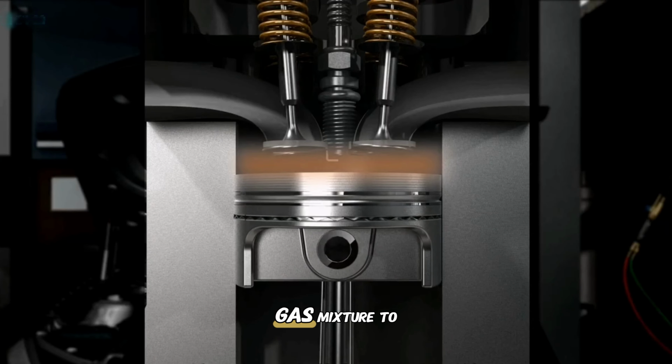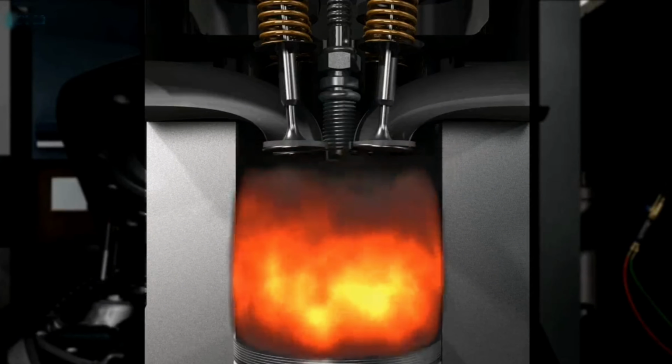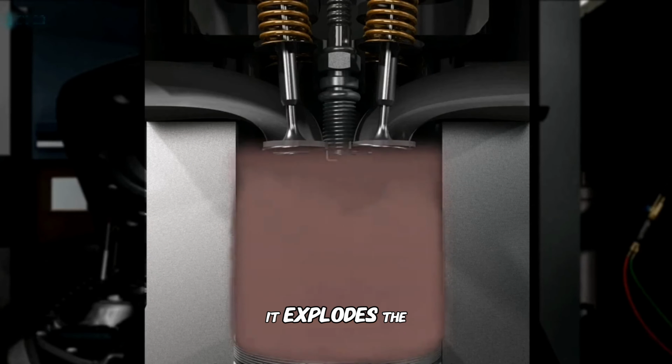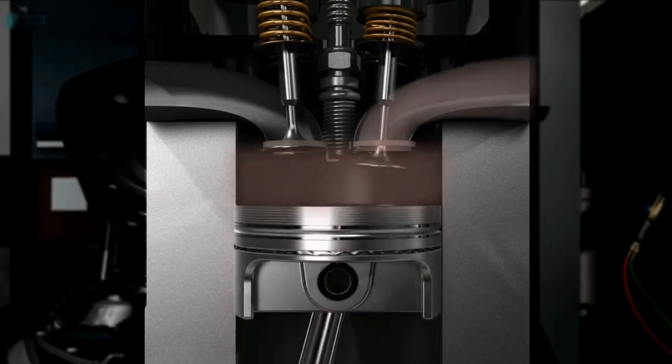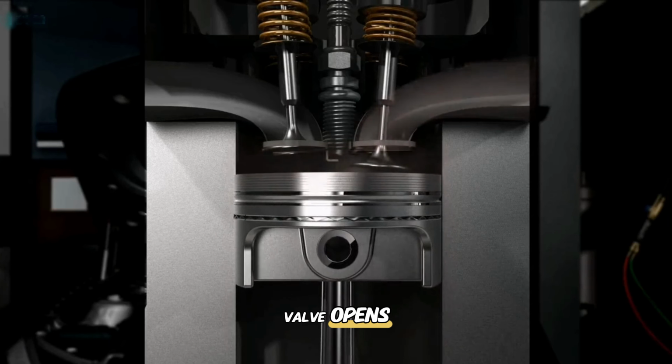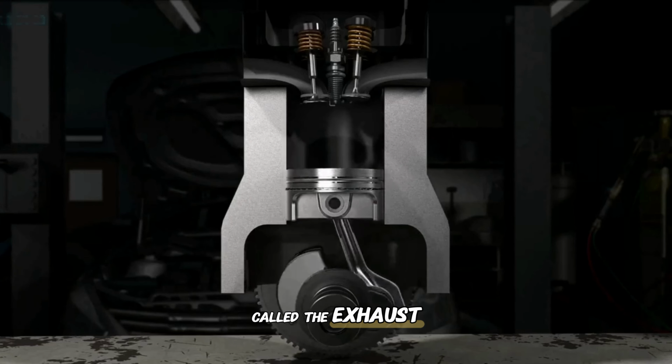This causes the gas mixture to be compressed at high temperature. This is called the compression stroke. When the spark plug ignites the compressed gas mixture, sparks are generated. It explodes. The force from the explosion causes the piston to drop. This is called the power stroke. Then the exhaust valve opens. The piston rises to release the exhaust gas. This process is called the exhaust stroke.